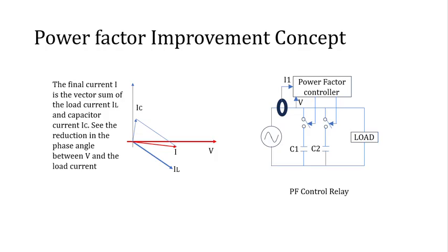It does this step by step to ensure that power factor does not become leading. Power factor must remain lagging. So it may have to disconnect some capacitors sometimes. A leading PF raises line voltage and puts all connected devices at risk. Hence, the step-by-step method.